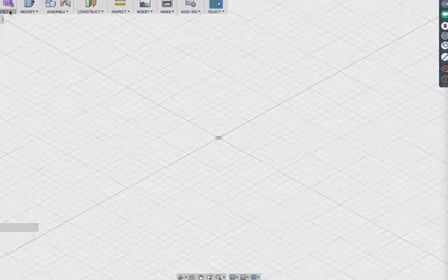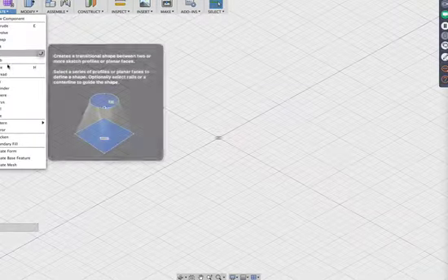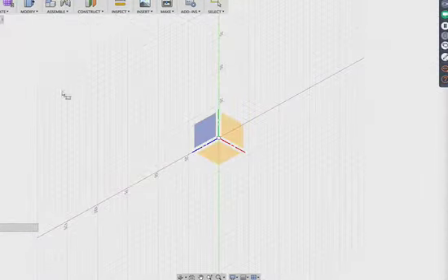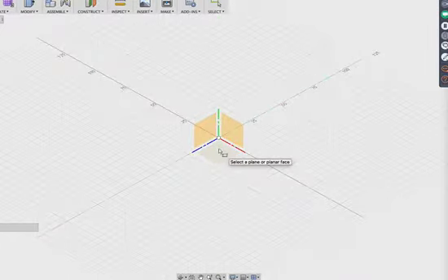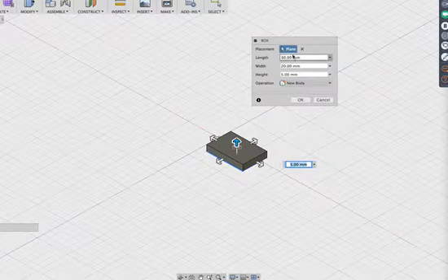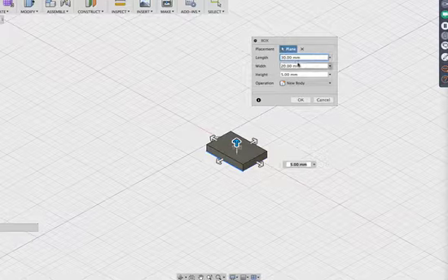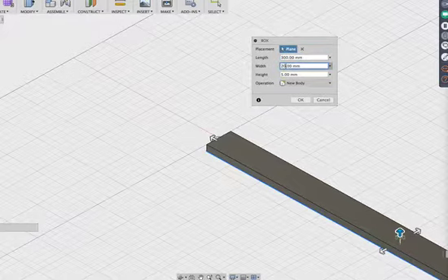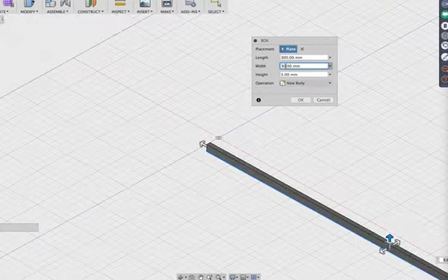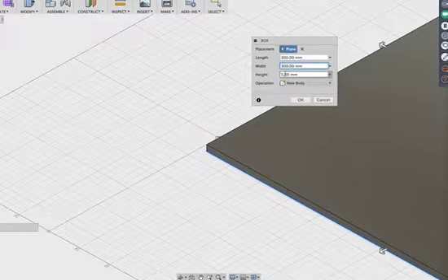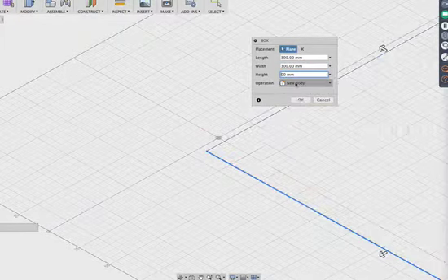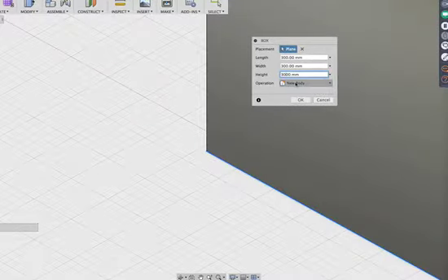If I create an object, if it's a two-dimensional object, it's a sketch. You can draw a line. But if you want to create a three-dimensional object, you will actually do it right here. So here's a box. I'm going to click on this plane right here, then the square. So there are the dimensions of said box. I'm going to make it 300 millimeters by 300 millimeters by, and I'm just making this up just to mess with it,